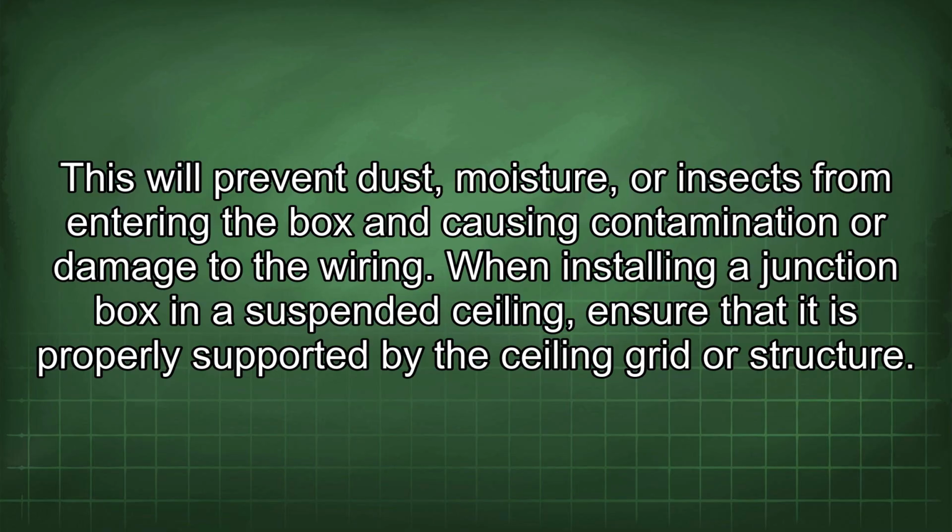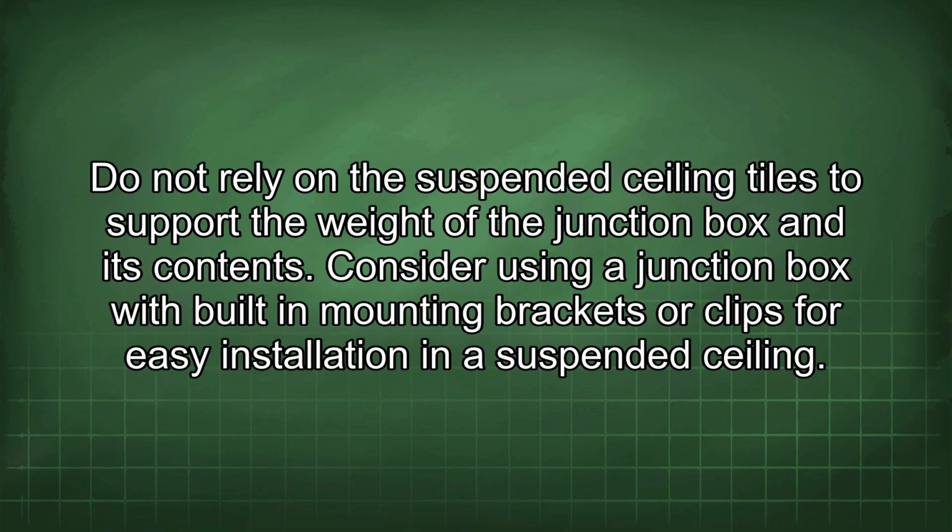When installing a junction box in a suspended ceiling, ensure that it is properly supported by the ceiling grid or structure. Do not rely on the suspended ceiling tiles to support the weight of the junction box and its contents. Consider using a junction box with built-in mounting brackets or clips for easy installation in a suspended ceiling.